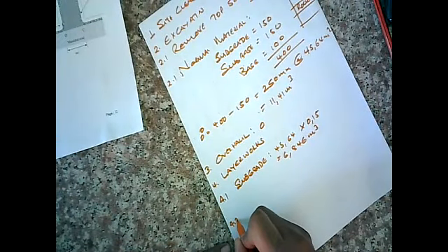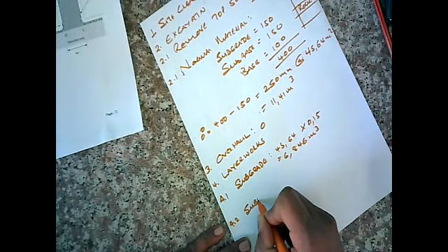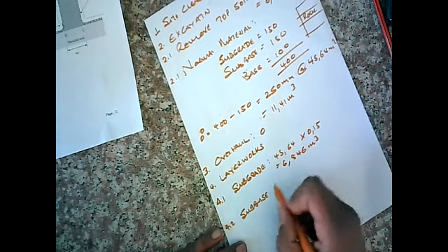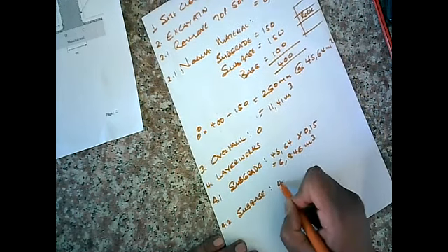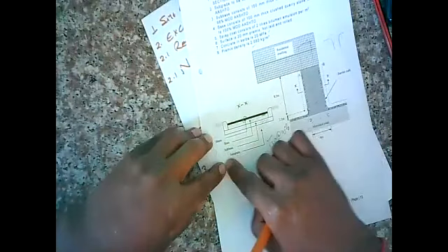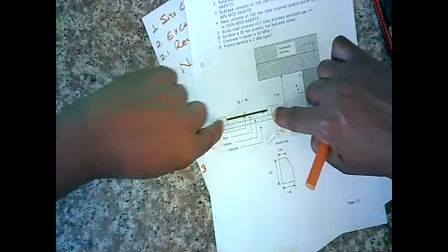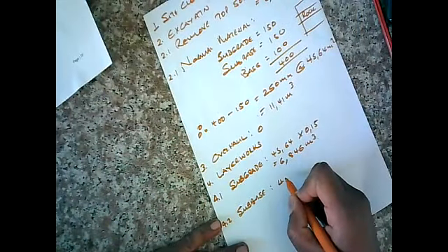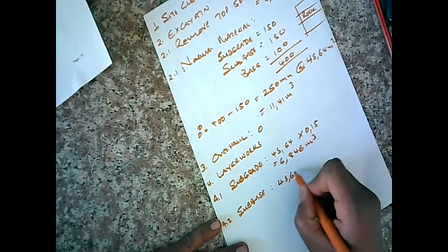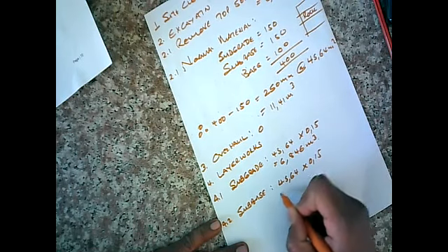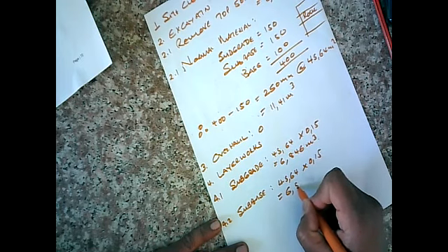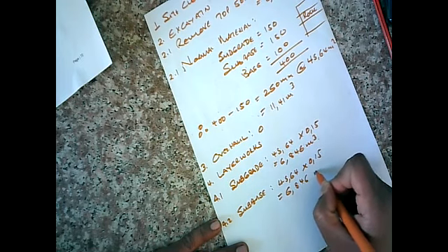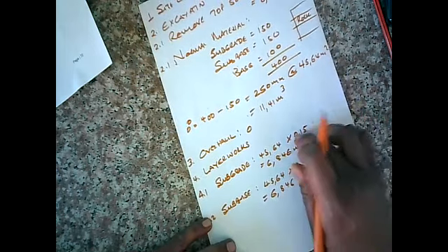Let's call it 4.2. Same area. How do I know it's same area? Because if you look at the subgrade, it's everything underneath. If you look at the subbase, it's from there to there. So it's everything underneath. Therefore, the area is still the same, and naturally, it gives us the same volume. Now, guys, this is like easy marks. 2 marks here, 2 marks here.